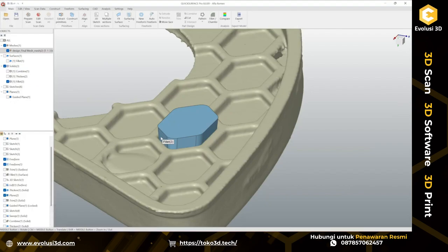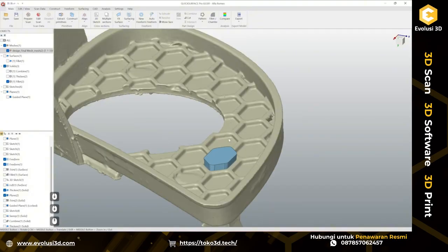What we need to do now is pattern it. Of course, we could do that in Sketch, but imagine after we had extruded all of them, we would have to add this fillet individually on each of them. So this would be much more time, much more work, to select all these edges.